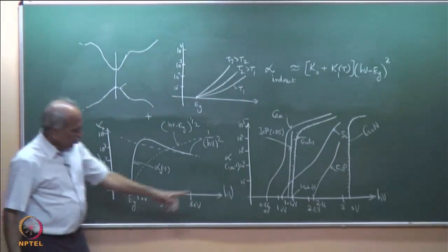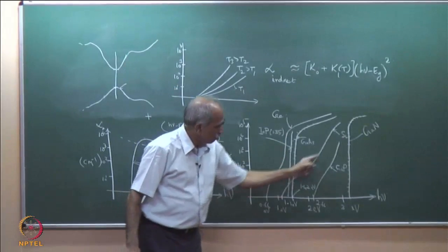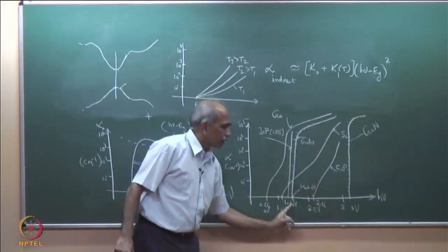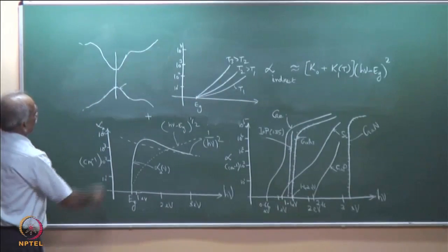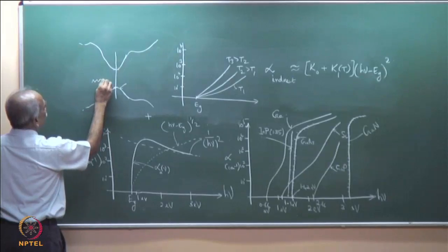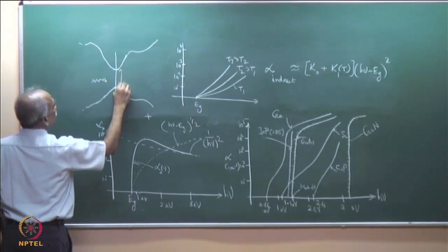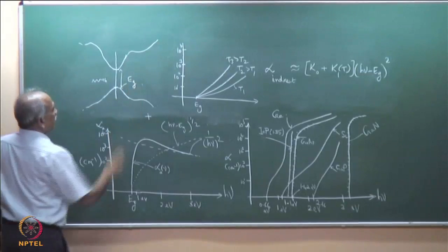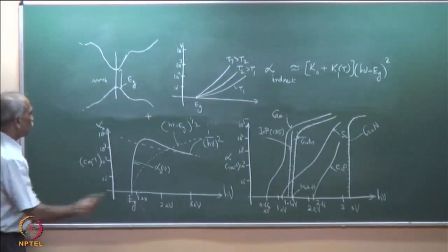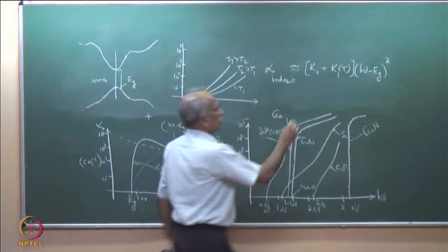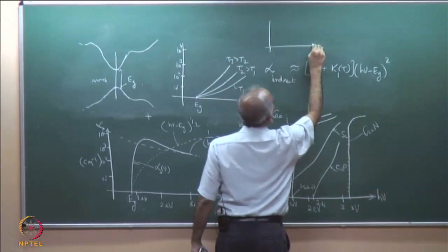Second, why in indirect band gap it goes like this, whereas in direct band gap it shoots up like this. Let us see the E-k diagram. As soon as h nu reaches Eg, so this gap is Eg, it gets density of states for interaction. Rho nu, if you recall, the density of states, rho nu, okay, let me plot it here.